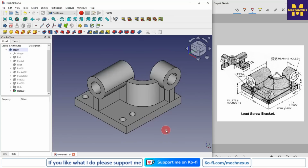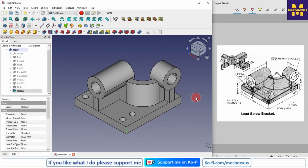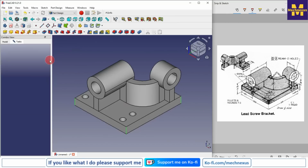And now if you see, the common note is that fillets and rounds are R3, which means that everywhere we have to provide a fillet of R3. So just select the edge, for example these 3 edges, and click on the fillet.